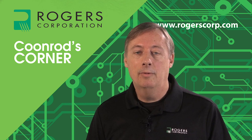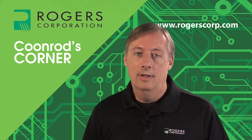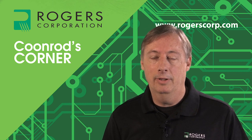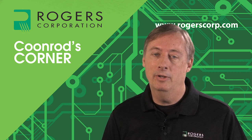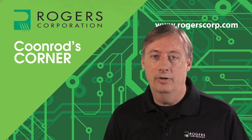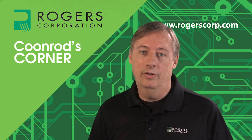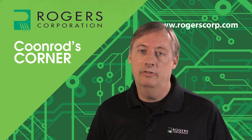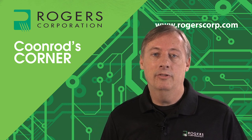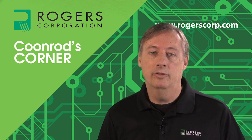In summary, thermal management is a pretty big topic for understanding reliability and thermal stability. So we talked about that some. Also, other aspects that can impact RF stability and reliability is the TCDk. Now, I did not mention TCDf, which is the dissipation factor temperature coefficient, and also TCIL, and that relates to insertion loss for the thermal coefficient. What that means is the insertion loss will change with temperature. We do have that data, but I did not have time to go through that here today. I would invite you to go to our Rogers Technology Support Hub, and after this video you will have a URL that will direct you to that website.